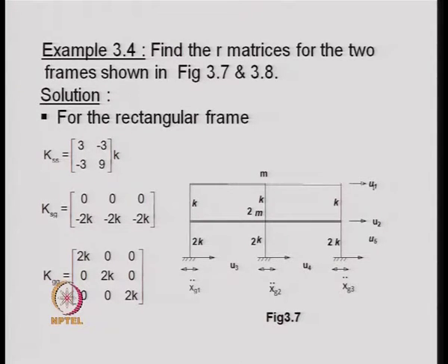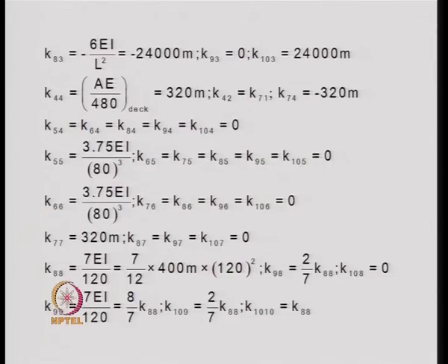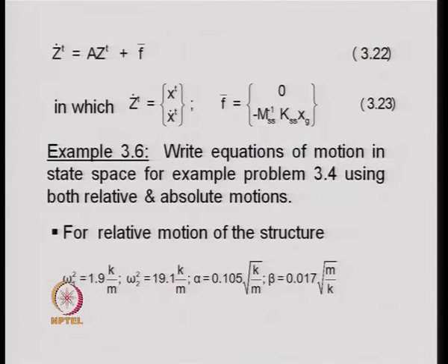Now, we obtain the C matrix. This approach is already known to all of you, that one can obtain the C matrix of a particular structure, provided we know the first few frequencies of the system. Here it was a 2 degree of freedom problem, in the sense that there are 2 non support degrees of freedom, so we had 2 natural frequencies.